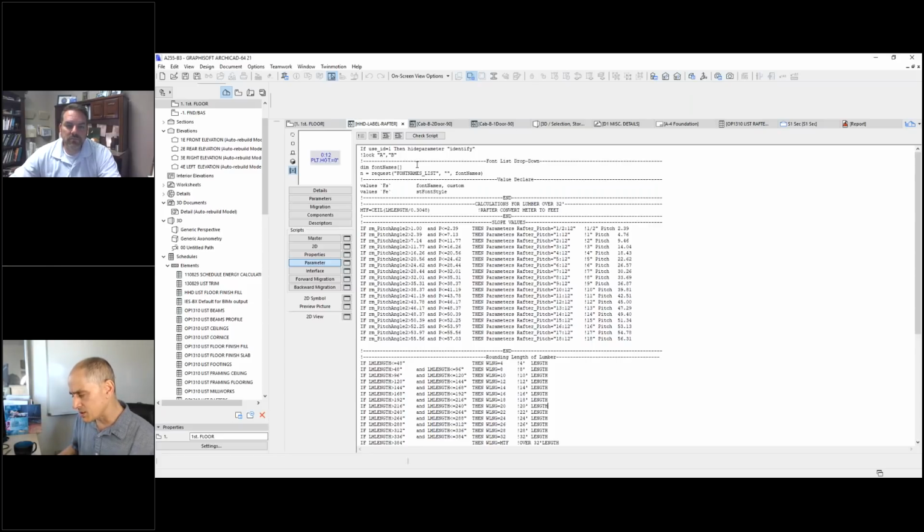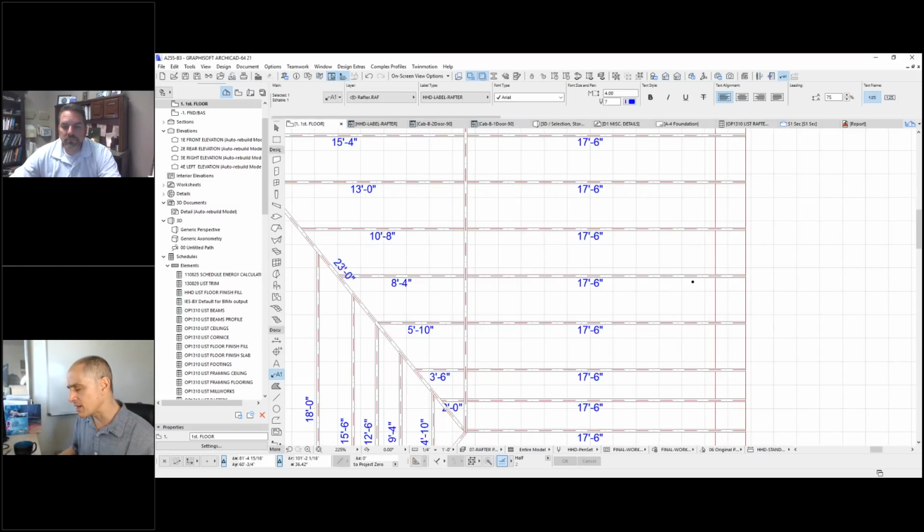Marie says, is there a difference between exporting composites, materials, etc., from the attribute manager as compared to using Hotlink from the external reference? There are more controls in attribute manager, but it's a manual process. Hotlinks will automatically update. So that's a very short answer. So this HHD label is a custom label that Chip created, yes. And can we show how to create it? No, because what Chip did was create something and script it. You can create custom labels, but to make something smart like this, you saw the lines of text.